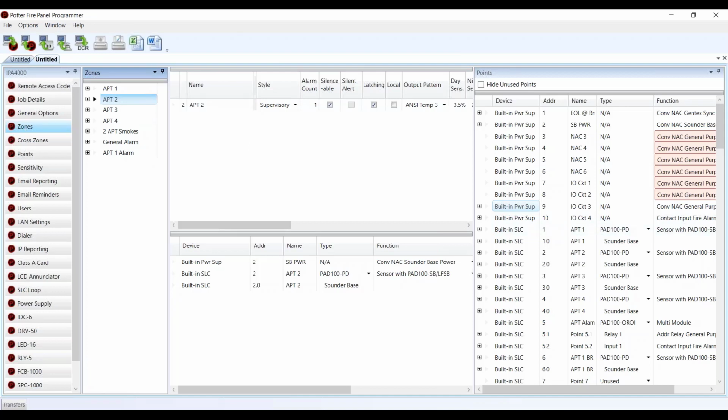Sounds like that was the scenario for the related to that question. So yeah, unfortunately there's not really a cleaner way to do that. You're gonna double your zones if that's the scenario where it's 2 smokes in the same apartment. That's what gives me my alarm instead of any 2 smokes in the building gives me my alarm. And hopefully both of those examples make sense to everybody, even if you didn't ask that question. If that doesn't make sense, let me know.